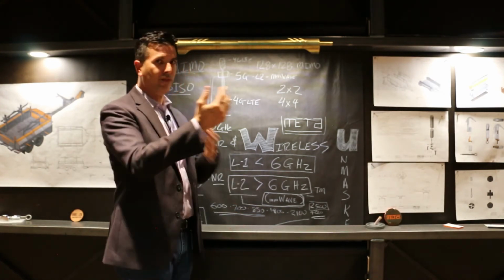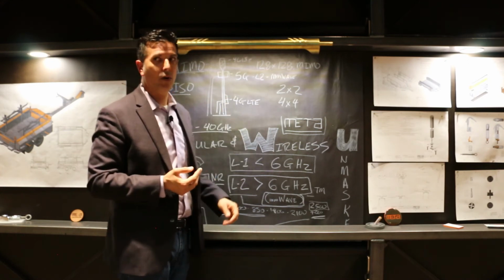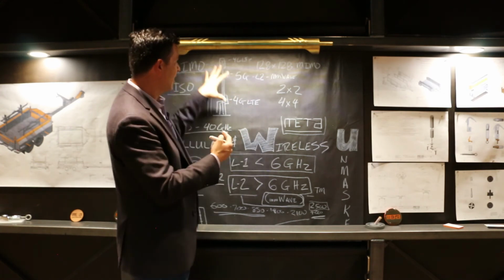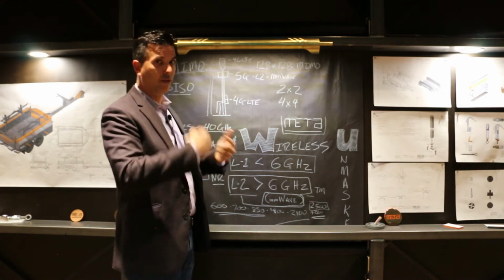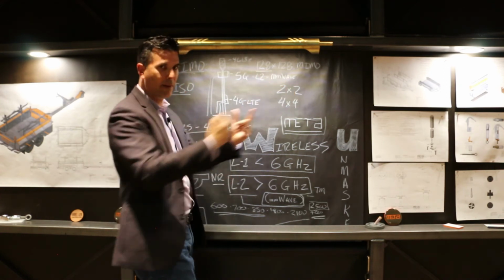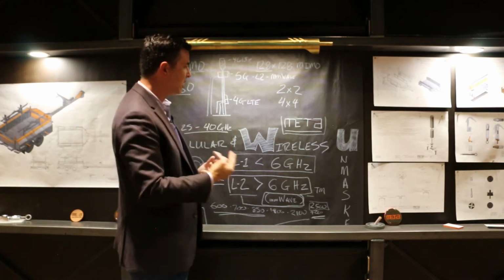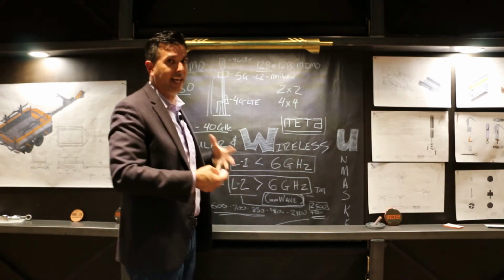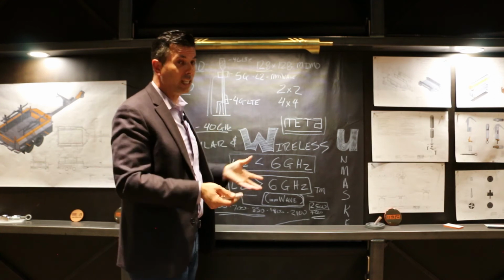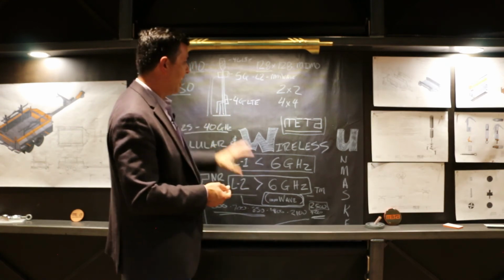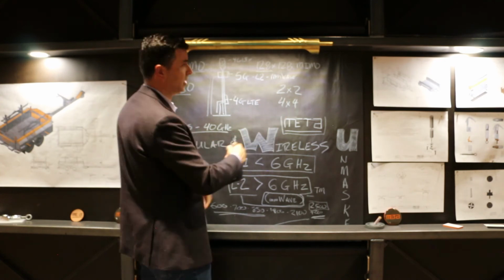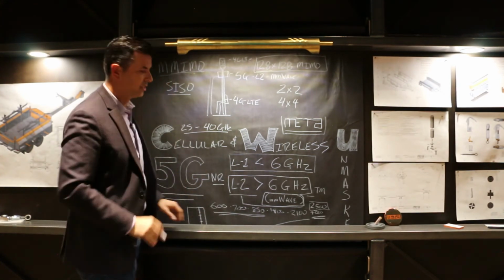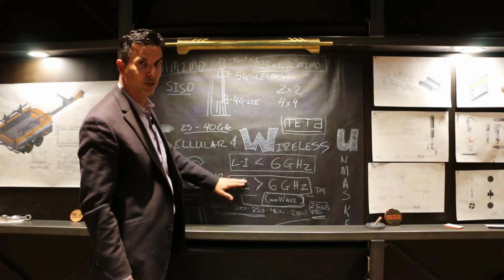So when you think about it, if your phone can take advantage of that massive MIMO, instead of having 2 or 4 pathways, 2 or 4 channels between the small cell or the macro cell and your phone, you have 128 separate pathways for that data. And that's why the level 2 millimeter wave 5G is so impressive. That's how you get to that 1 gig, 2 gig, sometimes 3 gig from these sites. They're really impressive. The high frequency band combined with the giant bandwidth in the channels and the massive MIMO, that's what makes that 5G so impressive in the L2, level 2 form.